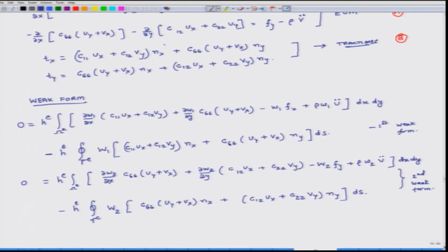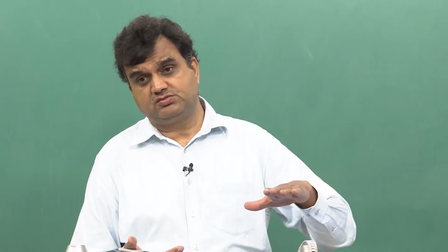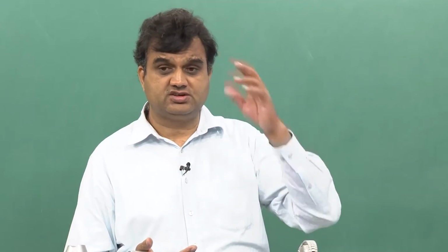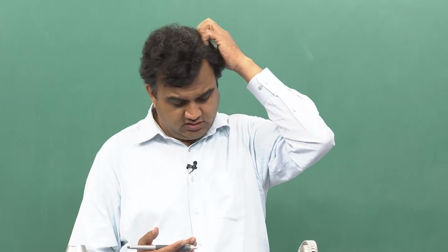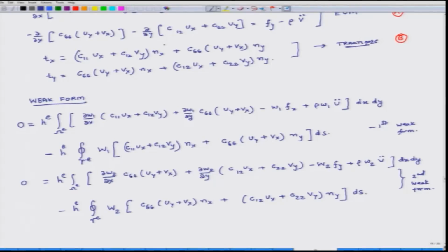And we had said that it is a plane elasticity problem. So, the entire body is enclosed between two parallel planes, and the distance between those two parallel planes is He. So, the thickness of the body is He. Now, in this weak form, if the thickness of the body is extremely small, then you go for a plane stress assumption and you accordingly choose your C's.